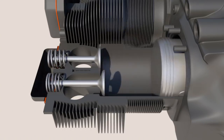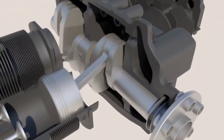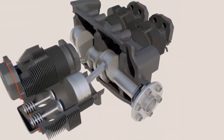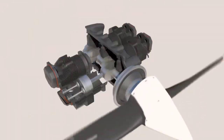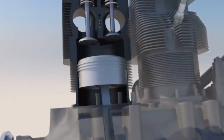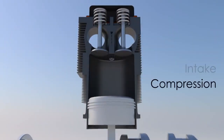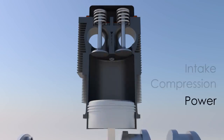These pistons are connected to a crankshaft, and when the pistons move in and out, that causes the crankshaft to rotate. The propeller is connected to the crankshaft, so as the crankshaft rotates, so does the propeller. The cylinders undergo a continuous four-stroke cycle. The four strokes are called intake, compression, power, and exhaust.